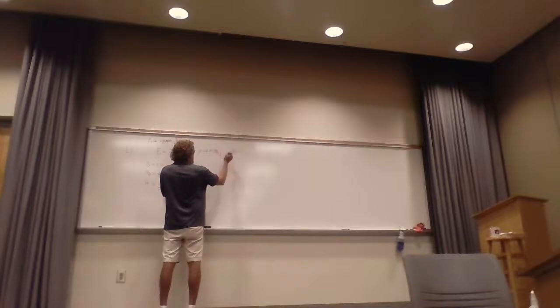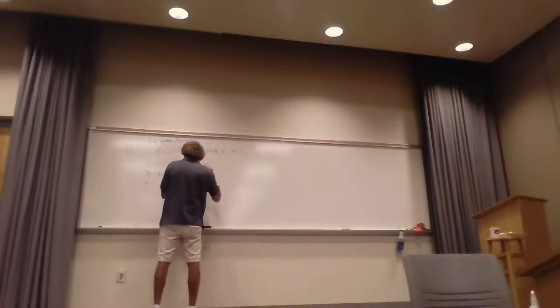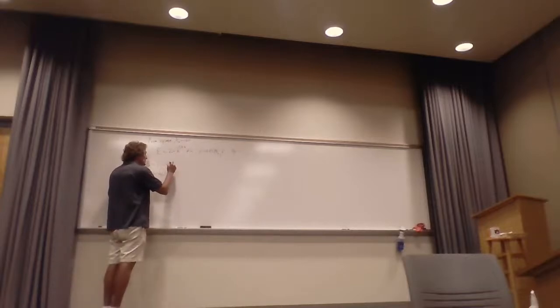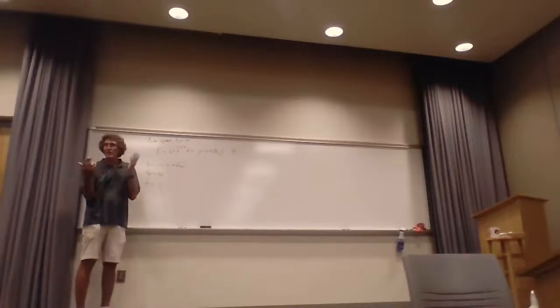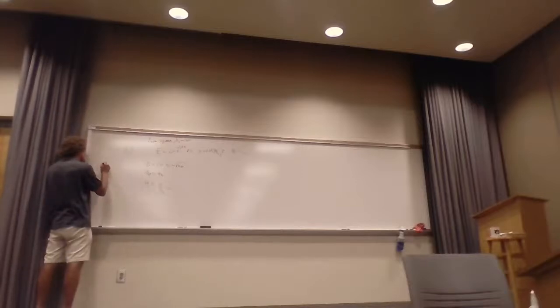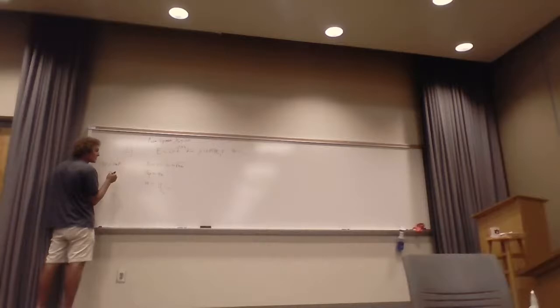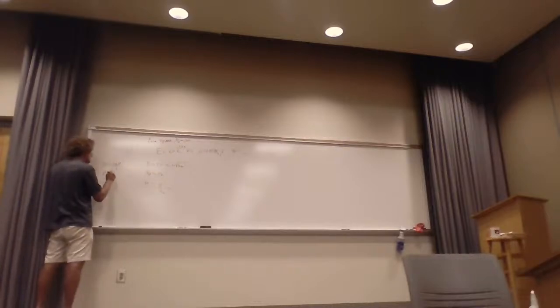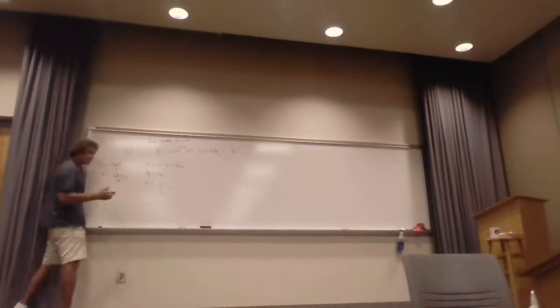And the frequency: there are several ways you can get frequency. Beta is equal to omega times the square root of mu epsilon. This is one way. When I look at that, 50 is equal to 2 pi f times the square root of mu epsilon, which in free space is 1 over c. So it's divided by c, and f itself is just going to be 50c over 2 pi. Do you agree with this?